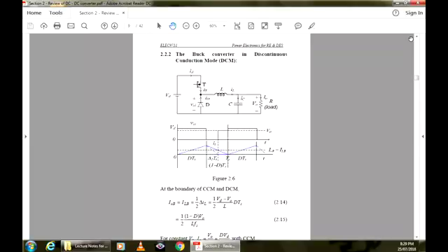Now, what happens if the conduction mode is discontinuous? In buck converter systems, we always try that the converter never operates in discontinuous conduction mode. In power supply circuits, across the capacitor there is a dummy resistance, so that the minimum load is always drawn, which is inside the power supply box. So there would be a dummy resistor here, so that the minimum load is always more than for this situation.